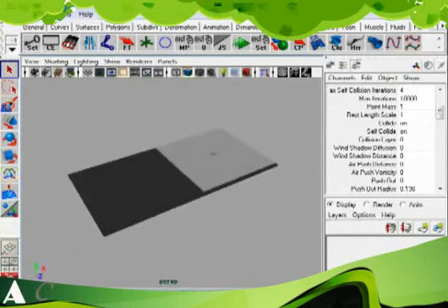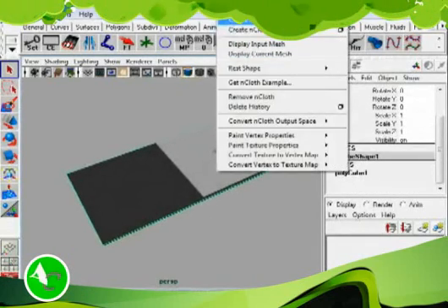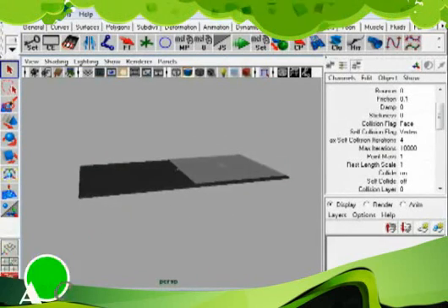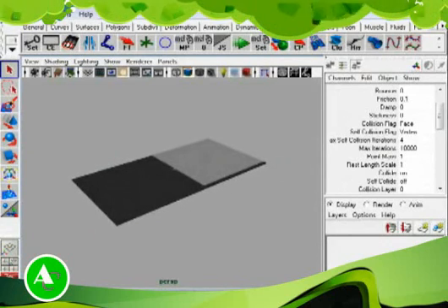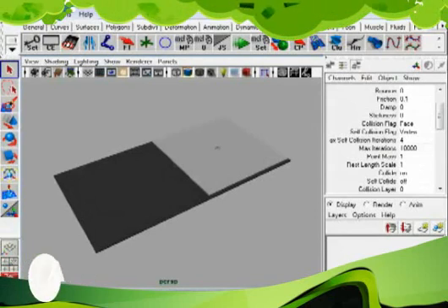So what we need to do is select the book cover, and then go to nMesh and create a passive collider. Once we have done that, hopefully we will have the piece of paper actually colliding. So it's currently working. Great. Once that has been done, we can set some attributes on the nCloth.